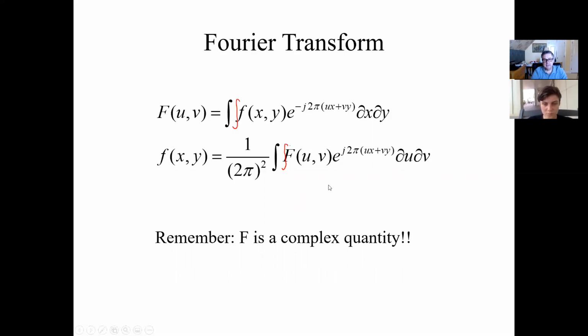And so, again, this is just a way of expressing the two-dimensional Fourier transform. If you're used to the one-dimensional Fourier transform, it extends pretty readily. Again, you can implement a two-dimensional Fourier transform by taking a one-dimensional Fourier transform, say, along the rows, and then a one-dimensional Fourier transform along the columns. So you can do it as two one-dimensional transforms. And the same, if you're doing a 3D Fourier transform, you can break it up into three sets of one-dimensional Fourier transforms. In fact, that's generally the way multi-dimensional Fourier transforms are actually implemented. Okay.